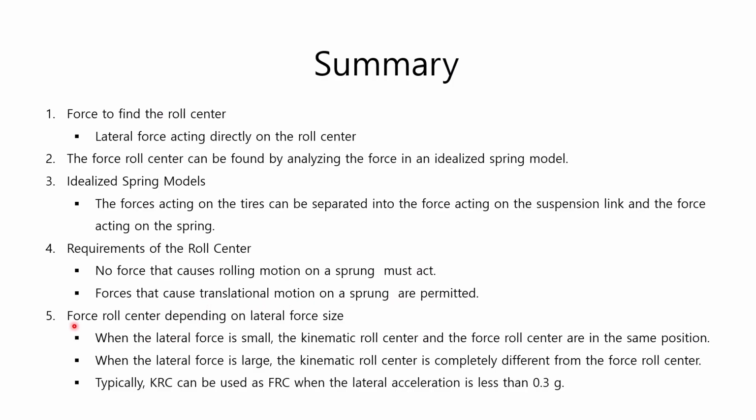Depending on the lateral force size, the force roll center has the following characteristics. When the lateral force is small, the kinematic roll center and the force roll center are in the same position. When the lateral force is large, the kinematic roll center is completely different from the force roll center. Typically, the kinematic roll center can be used as the force roll center when the lateral acceleration is less than 0.3 g.